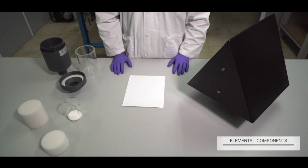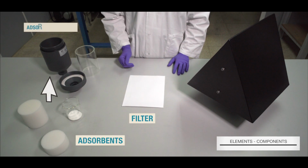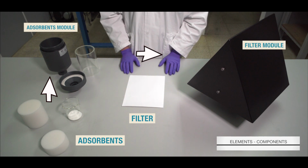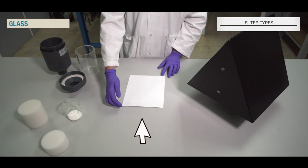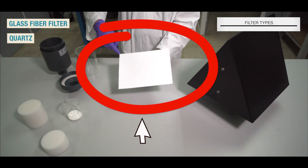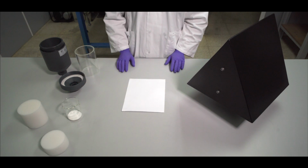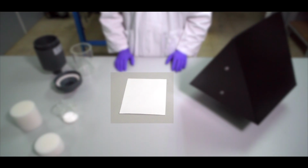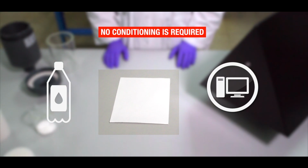As mentioned, the sample is collected in a filter and some adsorbents. These elements will be located in separate modules that will later be attached to the sampler. A wide variety of filters can be used, although the most common are glass fiber filters, GFF, or quartz filters. The shape of the filter depends on the geometry of the module to be used, and this is specific for each device, and therefore depends on the manufacturer. The filters can be used without a preconditioning process, although thermal conditioning can be carried out before being used.